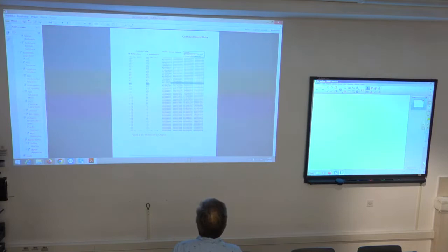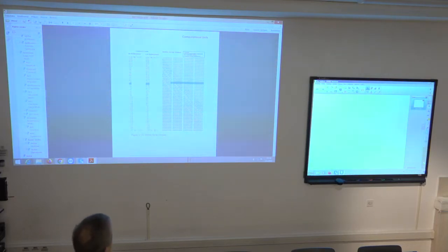Then it supports 128 shifts to the left or to the right. Of course, it doesn't make sense to shift something 128 times since the output register is only 32-bit wide. But nevertheless, the width of this register SE is 8 bits. So it is a 2's complement value, 8 bits. So theoretically, it supports shifting left or right by 128 positions.